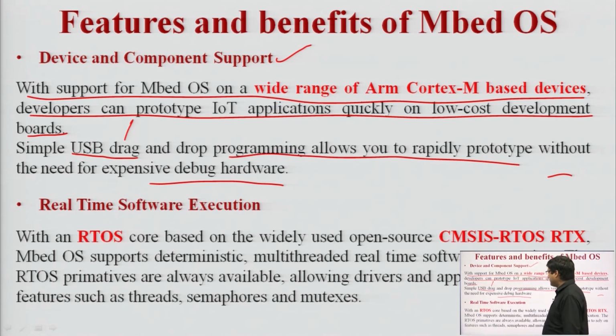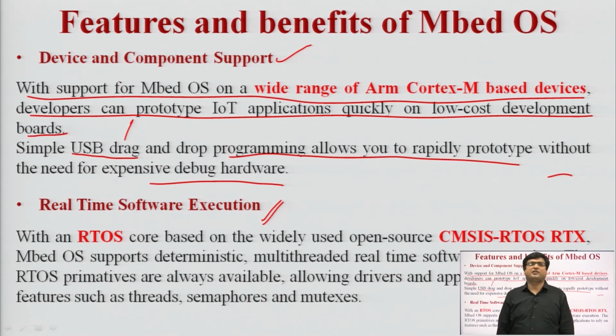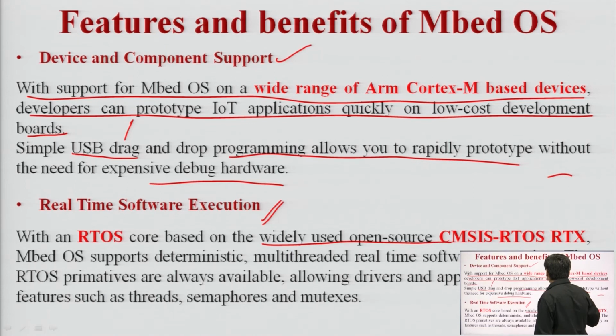It has real time software execution. This is the main feature, because all things are working in real time. For that you need real time software execution, not general purpose. So with an RTOS core based on the widely used open source CMSIS-RTOS RTX, Mbed OS supports deterministic, multi-threaded real time software execution as well.